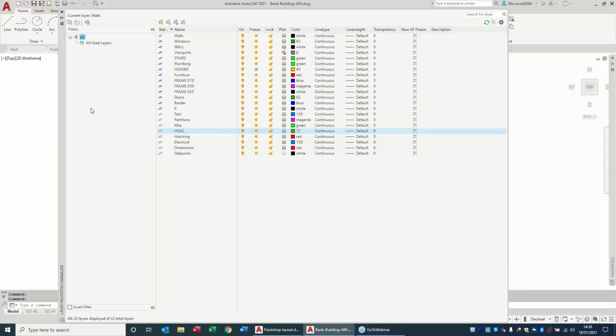Suppose you had a symbol in your drawing file called pump, a drawing on the system which you had inserted into your layout drawing. In that drawing called pump, there are several layers, and one of them is not being used in that drawing. If you make a block from that drawing and insert it into your layout drawing, that layer is being referenced by the pump drawing. Therefore, you cannot purge it. So that's one of the reasons you can't purge layers.